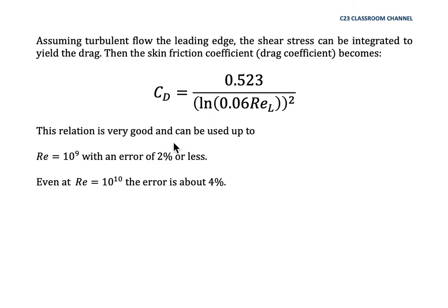The difference between the empirical method and the power law form is that the power law form is quite a rough calculation, and it will give you a little bit of error, might be less than 10% from the real one. But it is okay to use both of these methods because the turbulent boundary layer is quite rough. The boundary layer thickness is not static at a certain height, so it's different because the flow is turbulent.